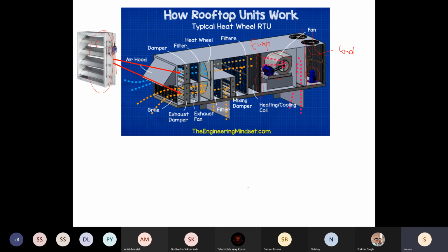So you have your evaporator coil here, your condensing coil here. This big blower is for the evaporator side only, because it has to blow air all the way through the ducts to your room. This is significantly more powerful, whereas this fan is less powerful. It is just to draw in outdoor air, pass it through the condenser, cool the condenser and blow out. So when we drew all the psychrometric processes, our focus was only on this side. We are not dealing with what is happening on the condenser side, as it is just sensible heat transfer.